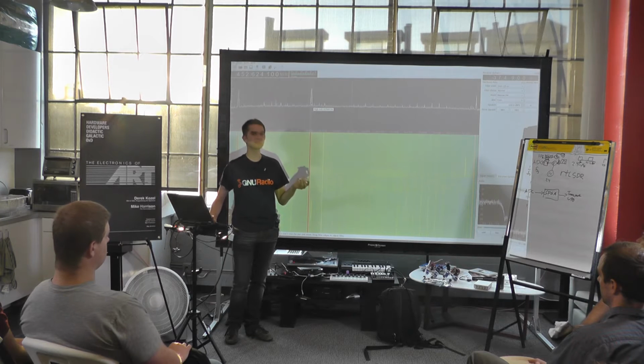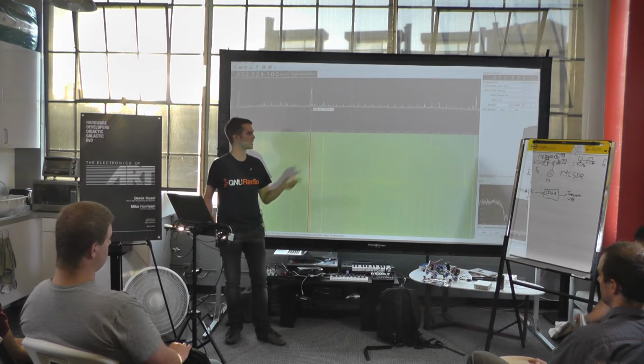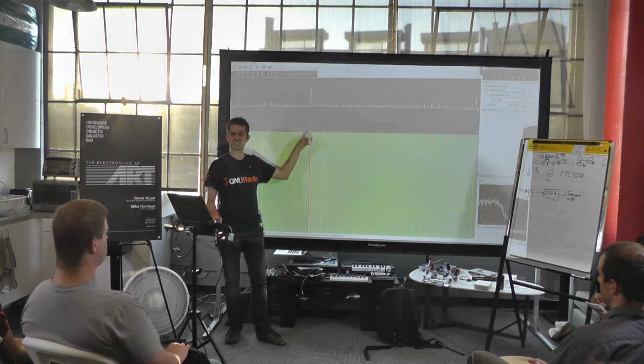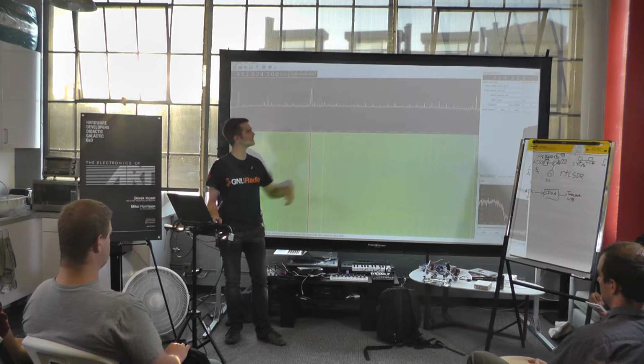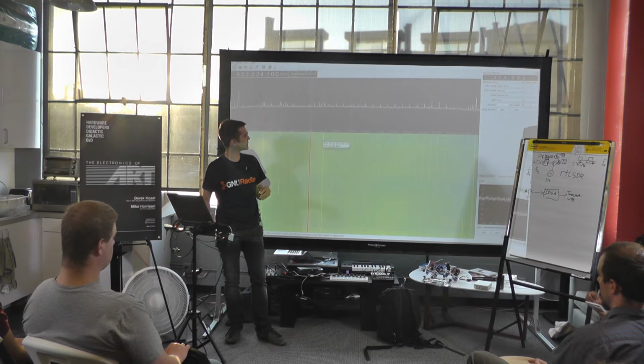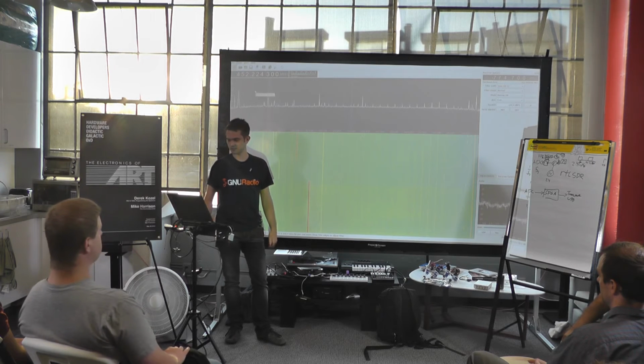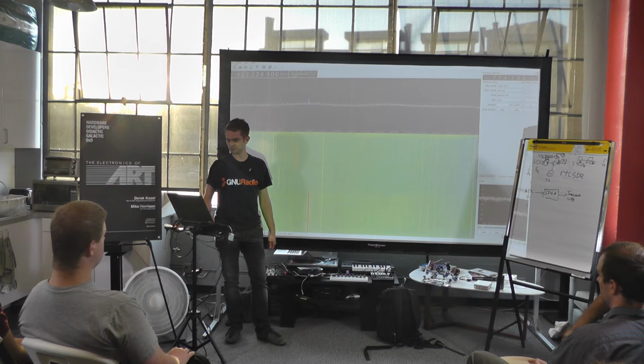It's basically a high-speed oscilloscope with a little bit of radio front end so that you're able to tune to different frequencies. This one is a digital system. You can actually hear the baud rate there. If we look for one of these more intermittent ones, these have a better chance of being analog. But this actually looks like a trunked public safety system.